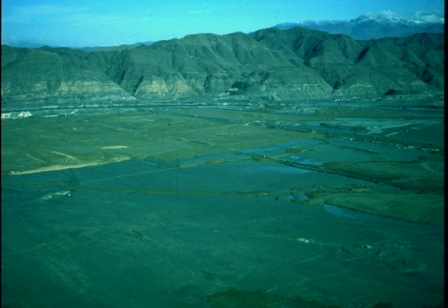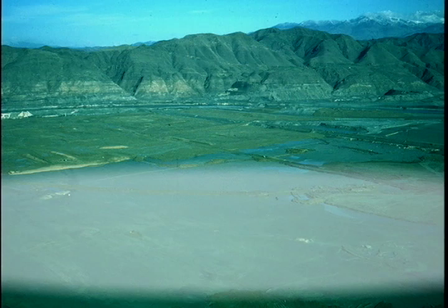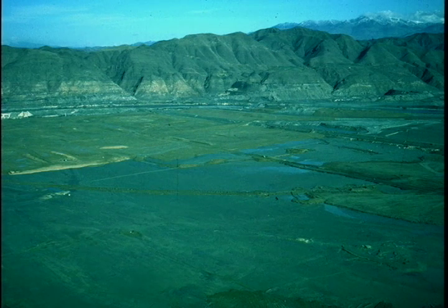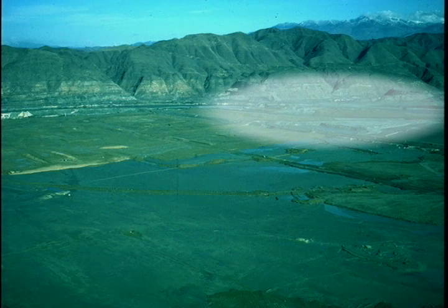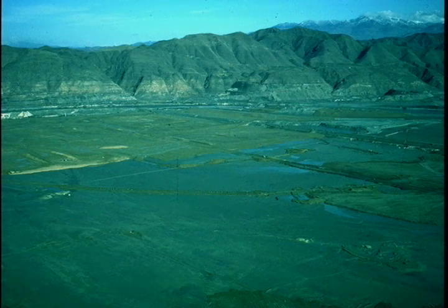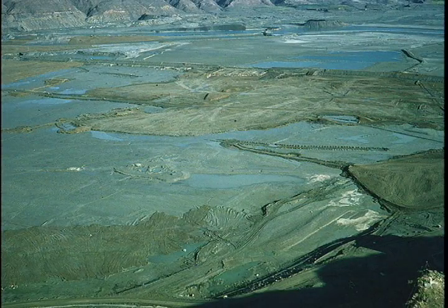The second picture is of the central portion of the blanket. In the foreground, black clay silt deposited during the filling of the reservoir is evident. In the distance, the placement of additional blanket material over the original blanket is evident. This is the area where the alluvium is the deepest and where most of the sinkholes occurred. The third picture is of the left-hand side of the blanket. An individual sinkhole is evident in the foreground.